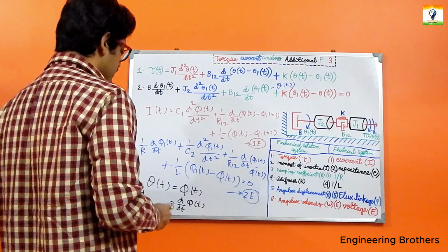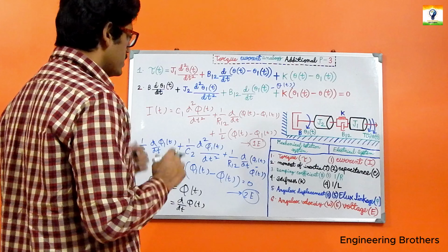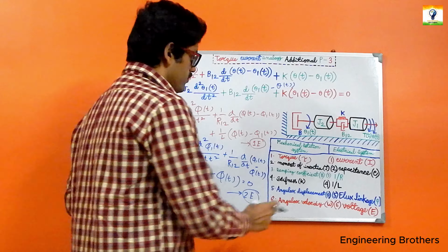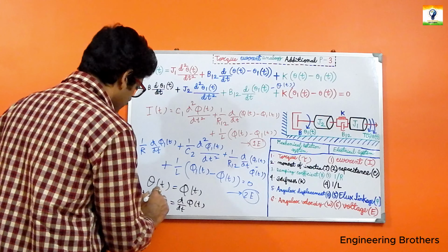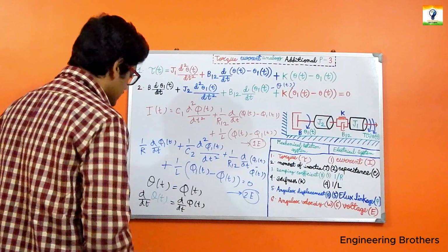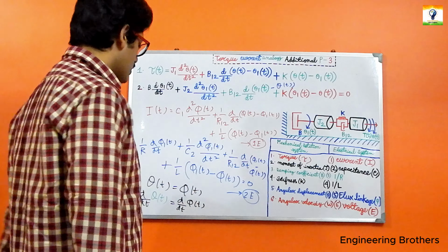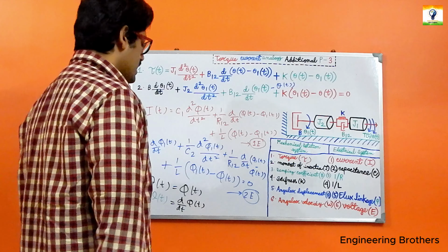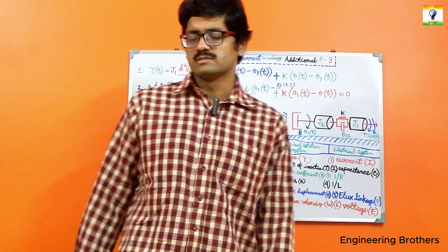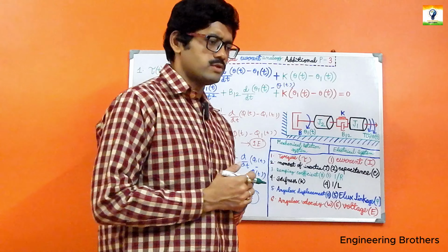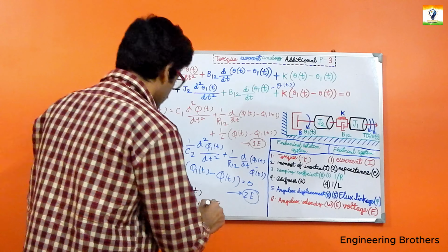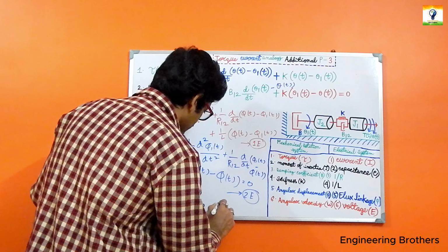And as the analogous concepts are quite considered, for our left hand side we have considered that one will be our mechanical part over here. So this one will be d dt of theta t, that is quite natural, d dt of phi t. And according to the definition for our electrical systems, we do know that the rate of change of flux with respect to time actually leads us to the consideration for our voltage over here. So this one will be our et.